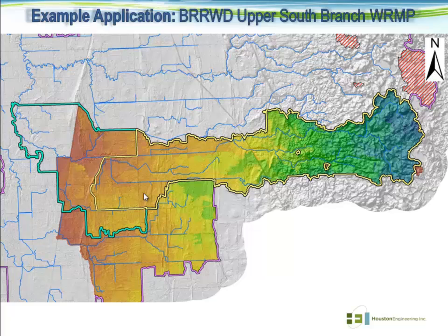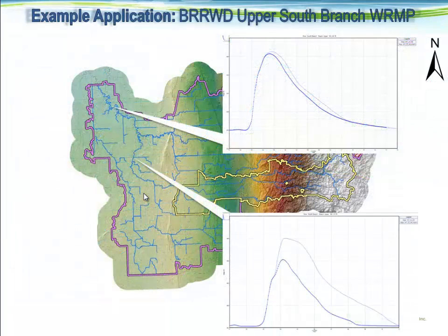So what you see here, this was again with the help of the hydro DEM, we were able to derive what the travel time characteristics are for this particular site, as well as points downstream. Once we know that, we can begin routing flood hydrographs into the site and see what the corresponding outflow flood hydrograph would look like as a result of implementing that site. By comparing existing and proposed conditions, you can see here hydrographs from a couple HEC RAS model runs, where just as you'd expect with detention sites, the closer you are to the site, the more benefit you see, which you see in the bottom hydrograph, a substantial reduction off the peak, as well as substantial volume reductions.